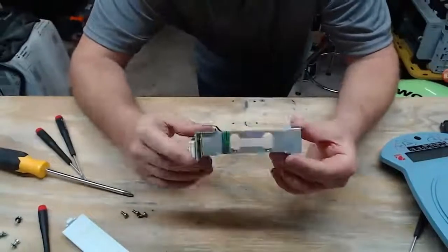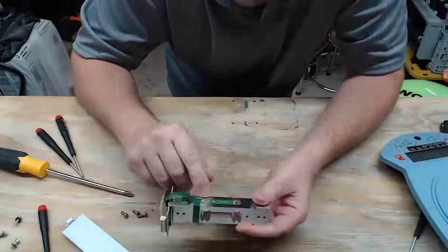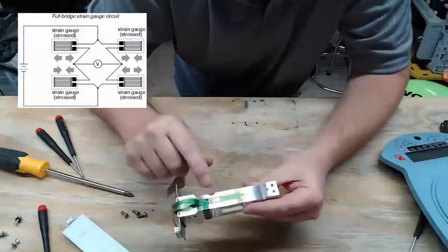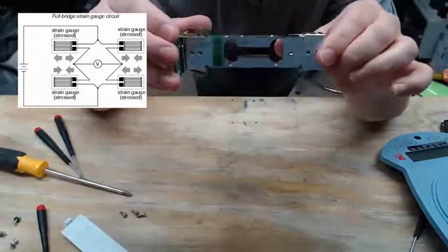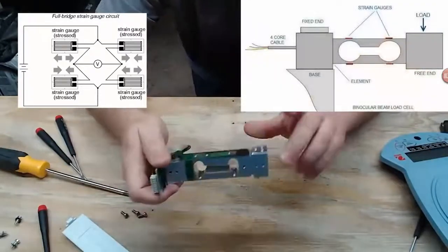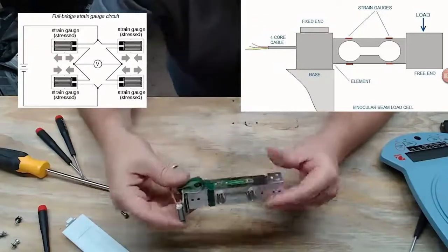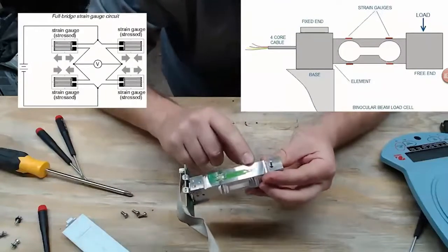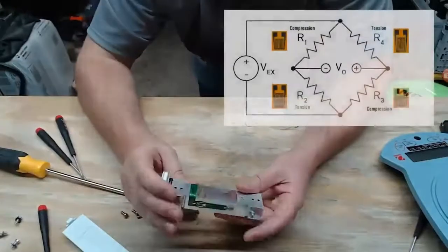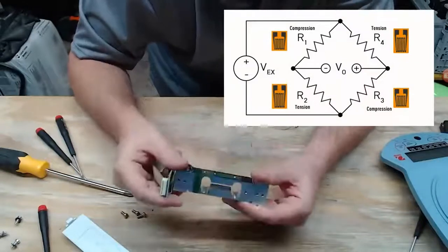This is a load cell, and this is a fully functioning one too. What we have here are strain gauges. See here, here, here, and here. And you see how it's got that dog bone. Because as you place a weight on one side and the other side is anchored down, it creates a compression on one side and an expansion on the other side. And on the opposite side of the load cell, you get the reverse. So you have 4 points of measurement, which give you a very stable reading and a lot of resolution.